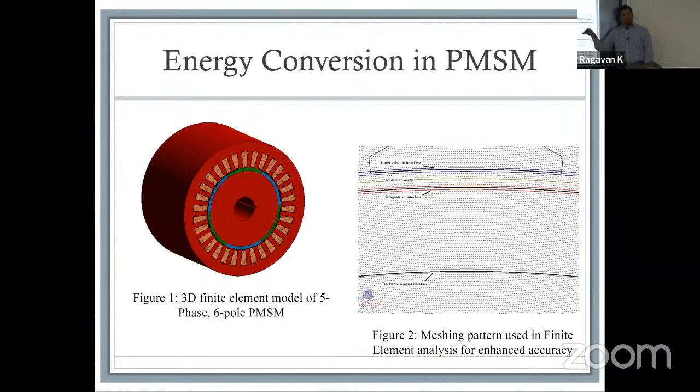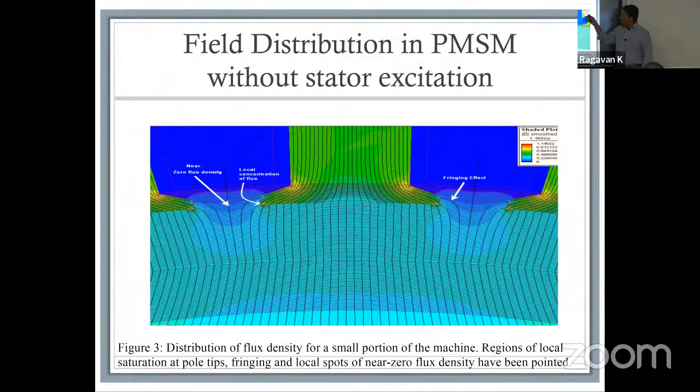I used this software for a very long time, and one of the challenges that I found was the meshing. That's not the reason we moved away from this, but the challenge of creating something like this, when you are looking at the microscopic, this definition of magnetic field required you to have a uniform mesh distribution. Otherwise, the calculation of your fields in the middle of the air gap was not accurate, and more importantly, not reproducible.